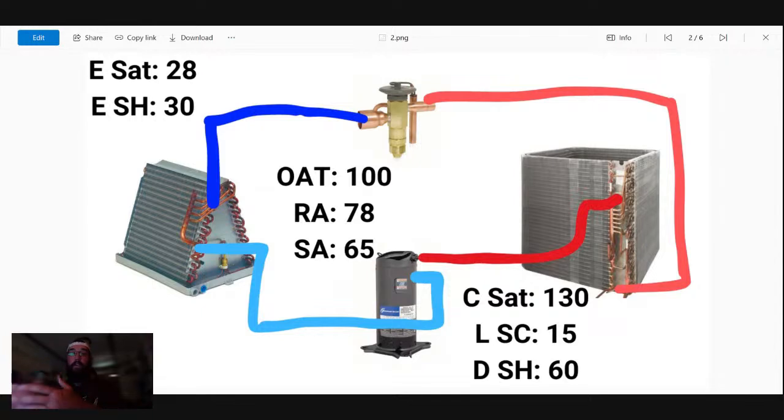My preference is cork tape. I know not everybody appreciates that, but I do really like how well and how long cork tape holds up. I like it a lot better than the foam tape. I've had a lot of issues with foam tape. So yes, the sensing bulb will roll out via visual inspection. It is okay.